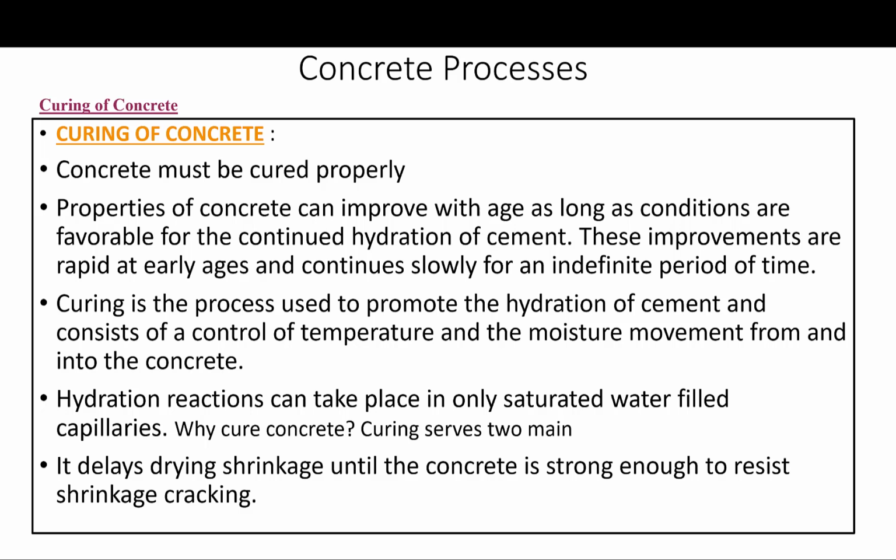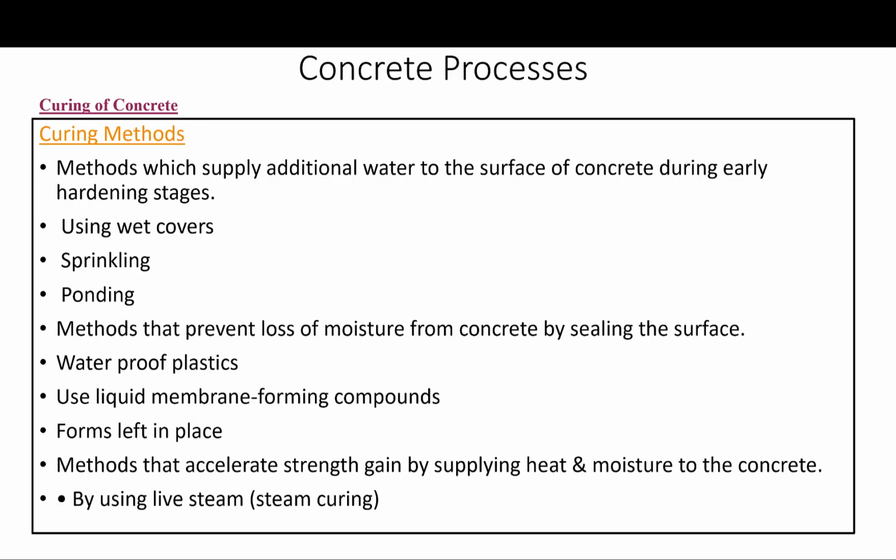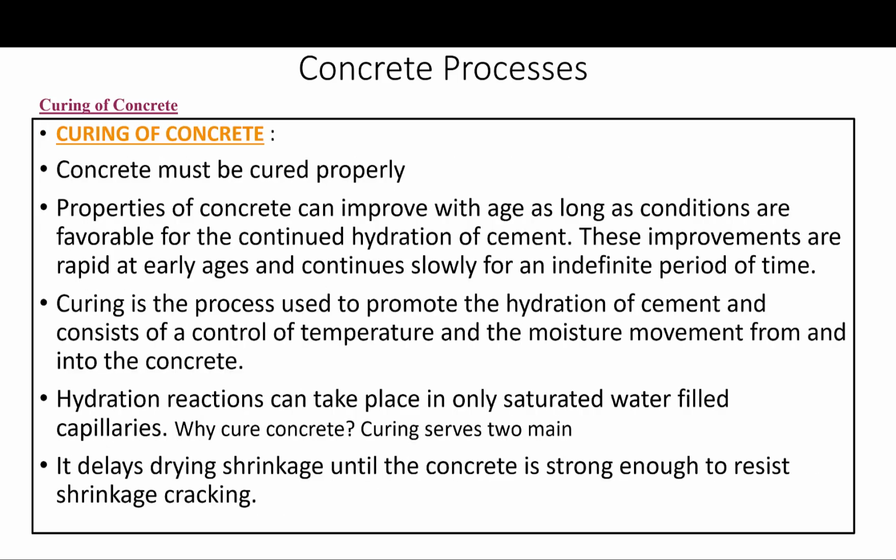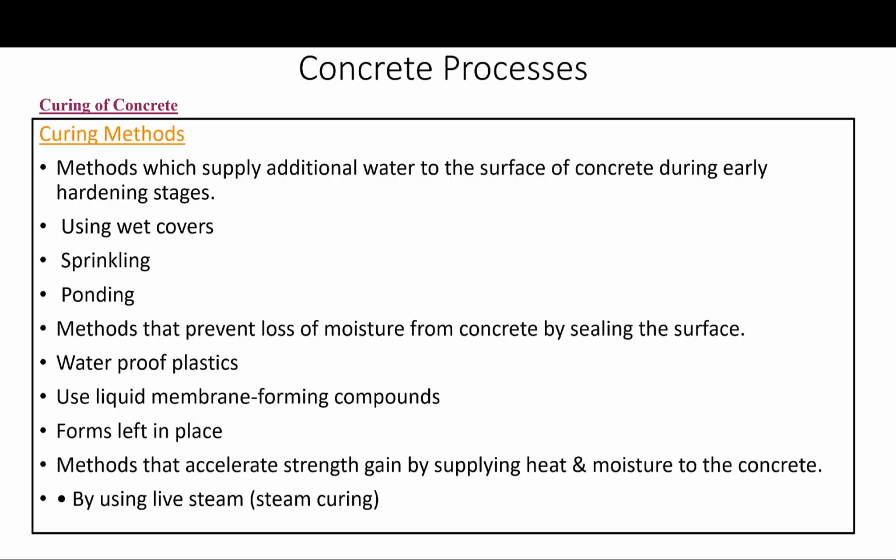So why cure concrete? Curing serves two main reasons. It delays drying shrinkage until the concrete is strong enough to resist shrinkage, and also, as I said, it promotes and continues the hydration process.